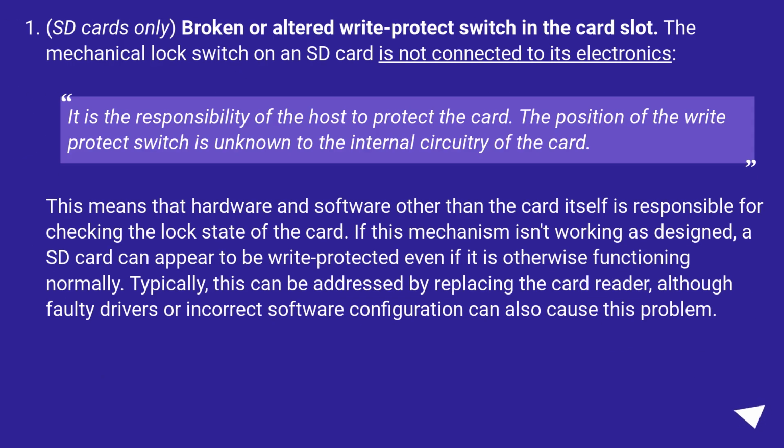SD cards only. Broken or altered write protect switch in the card slot. The mechanical lock switch on an SD card is not connected to its electronics. It is the responsibility of the host to protect the card. The position of the write protect switch is unknown to the internal circuitry of the card.